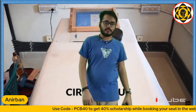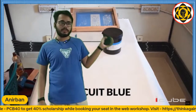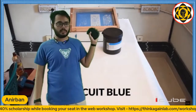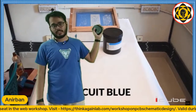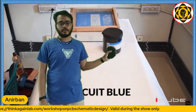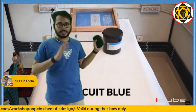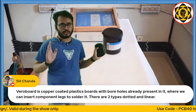Next is circuit blue. So this is basically the different ink I was talking about. This is what we will use to make those copper connections. So this is a very specific high-end PCB making paint, and that's why it's maybe a little bit expensive. You guys might find some cheaper solutions, so you can go with it. It's not necessary to use this compound only, but make sure that it's PCB class. It's not normal paint. Otherwise, you will make a big mess, and the PCB won't work obviously.